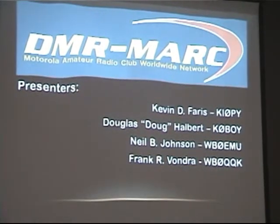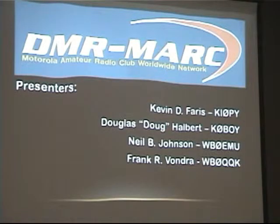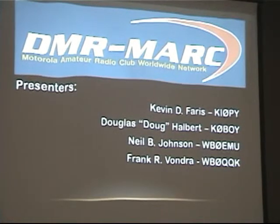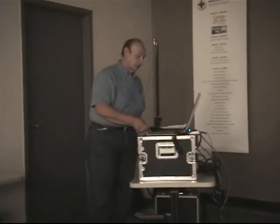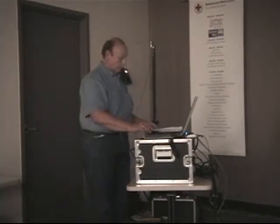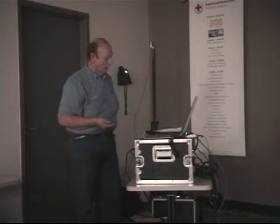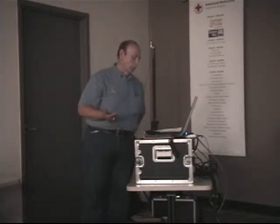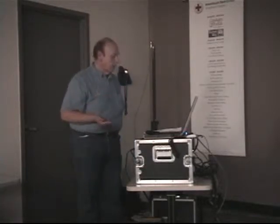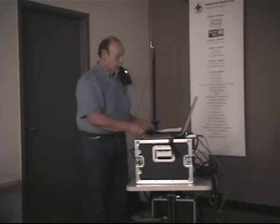The DMR standard was published by the European Telecommunications Standards Institute, ETSI, like Neil's already said. The organization was started in 2005 with the goal of providing digital communication systems that are low cost, low complexity, and interoperable between equipment vendors. The DMR standard specifies the air interface between radios specifically to use the following: two-slot time domain multiple access, or TDMA, 12.5 kilocycle channel width, 4 FSK digital modulation, and used on frequencies anywhere from 30 megahertz to 1 gigahertz.